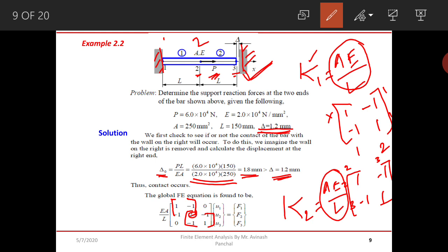Here this 2, the central element, the second diagonal element, is given as 2, because the last element of k1 and the first element of k2 both get merged, since these correspond to node number 2, so they are added and the other values are kept the same. Okay, so now we will go to the next